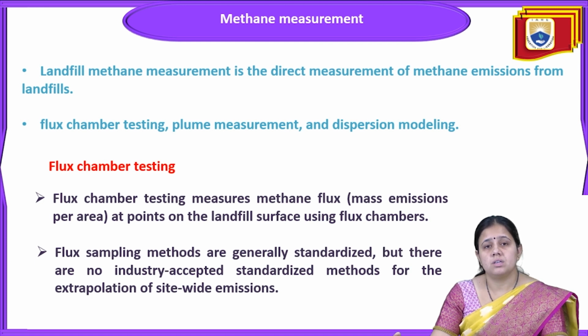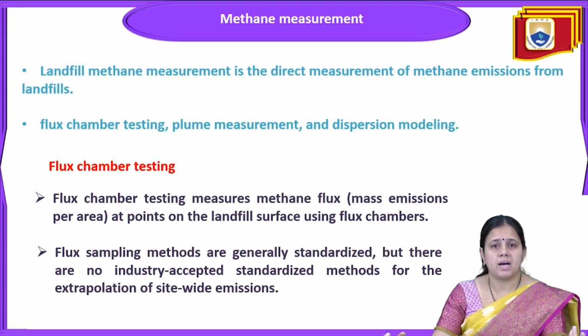the landfill. This methane is a very dangerous gas because it is a greenhouse gas, and methane production will create nuisance and odors in the vicinity of the landfill area, creating an unpleasant condition for the local public. That's why monitoring of this methane gas is mandatory, and it is required because methane is also a very useful gas. If we can utilize this methane for electricity generation or other products, that will be another beneficial effect of methane production.